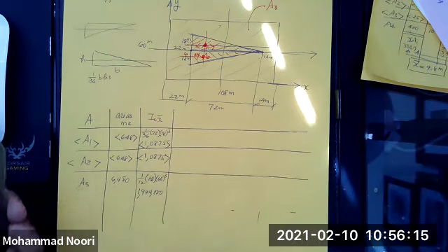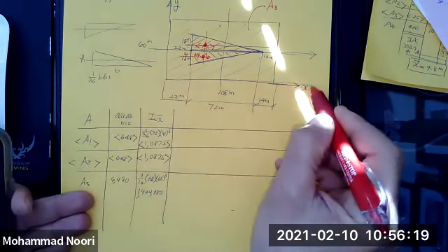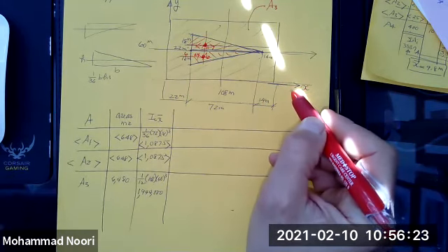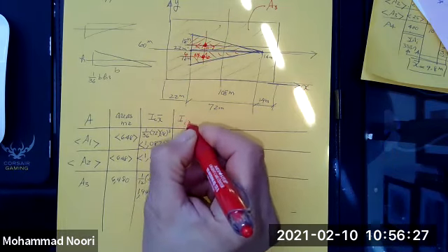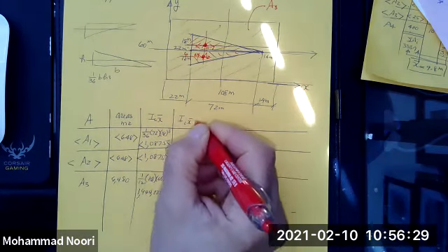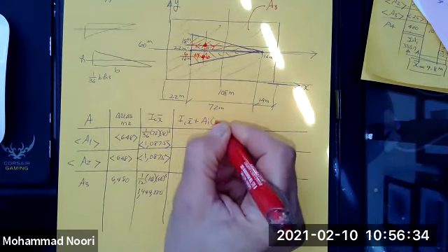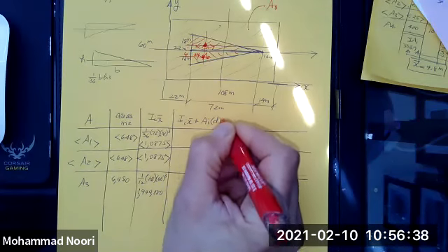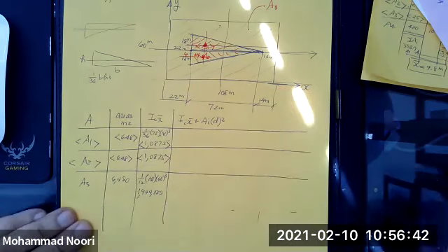You want the moment of inertia of this shape about this axis. So you need to add these values plus each corresponding area times the square of the distance from the centroid of that area to this axis.